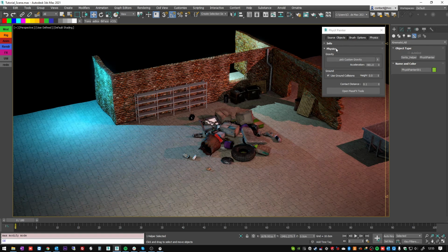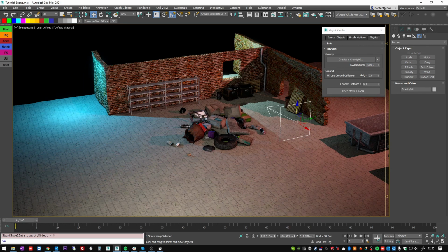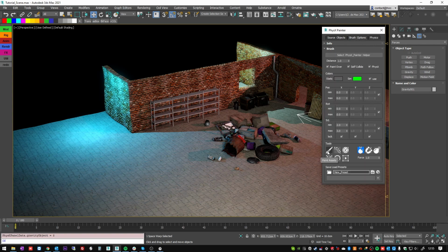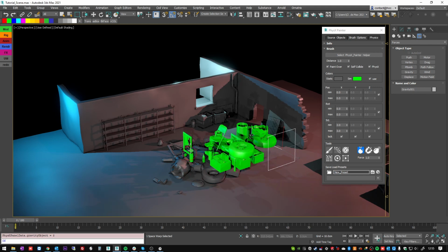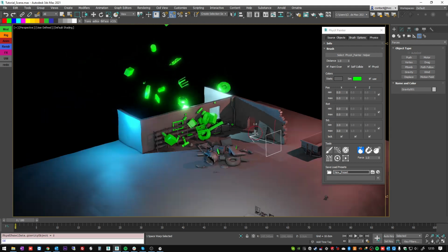You can also use a custom gravity object. So to do that, you go to the 3ds Max Forces and create a gravity object. And you can pick it here. So by default, its value is 1, but you should increase it quite drastically to have it work. I mean, it should depend on your scene units. So now if you paint assets, they will use the custom scene gravity, okay, and they will be projected here.